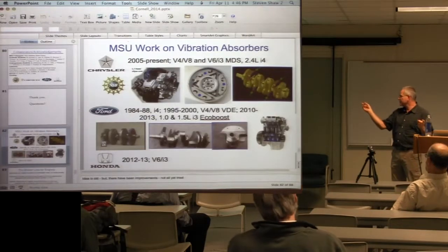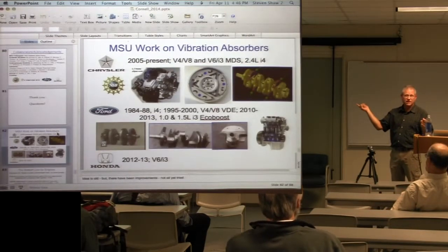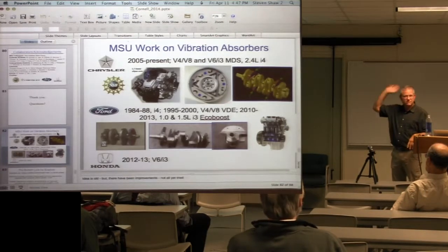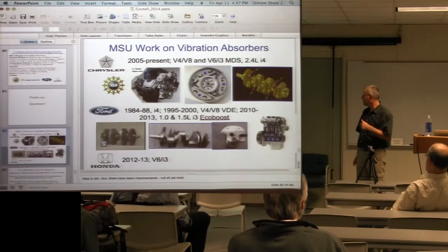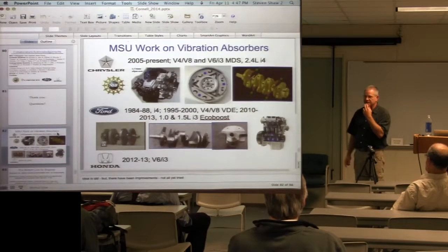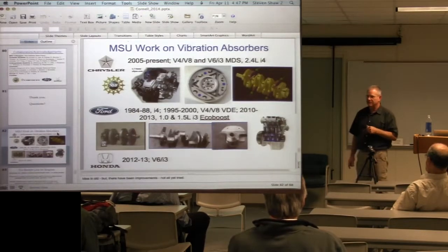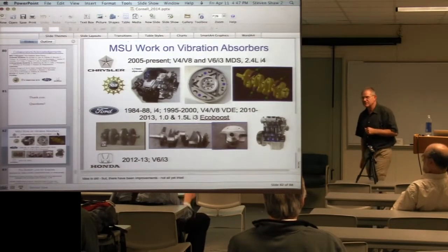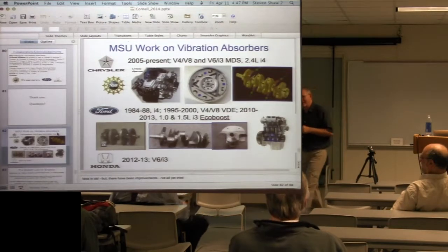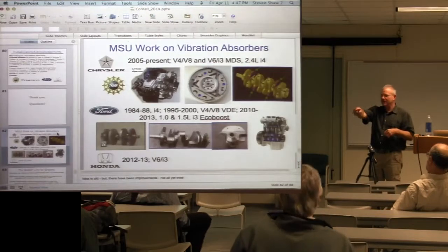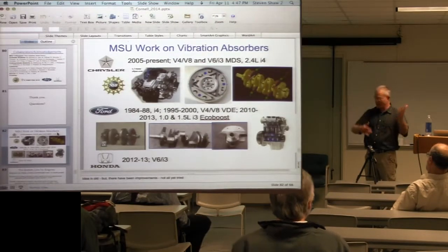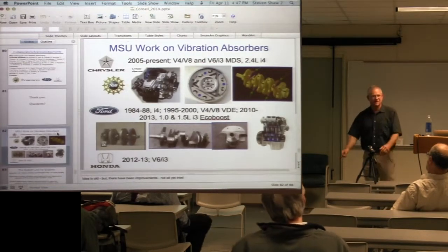That's one reason people, when I show this in engineering, they always say, well, how come these aren't in cars? They've been around in light aircraft forever. And the reason is that the car companies are afraid because of the transient environment. Your airplane, what does your engine run at? Like 2,300 RPM all the time, right? Virtually. But anyway, in aerospace, like helicopters and light aircraft, they run at pretty much a constant RPM. The auto, it's all over, up and down.